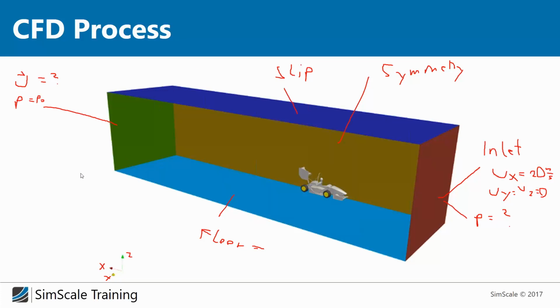Then Hermann wants to know why P and Px are 0. Px is nowhere 0 because there is no Px, Hermann. P is a scalar. If you want to know why P at the green surface is 0, the reason is that it's our environment pressure, P0. It can be 0, it can be 1000, 5 million, it does not matter, because pressure is about pressure differences. But if you want an understandable example, P0 on Earth is around 1 bar.